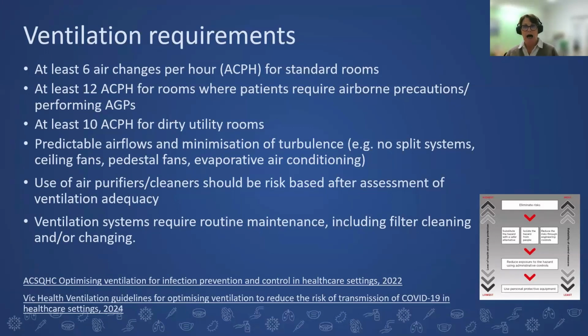Now, if we look at higher risk rooms, where we're likely to have to apply airborne precautions for patients who are suspected or confirmed to have a respiratory virus, for example, or we're performing AGPs, then it should be at least 12 air changes per hour.